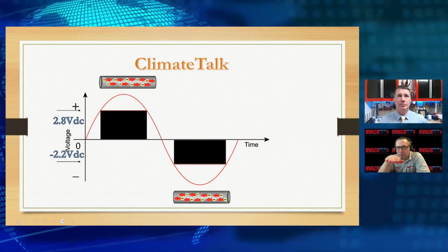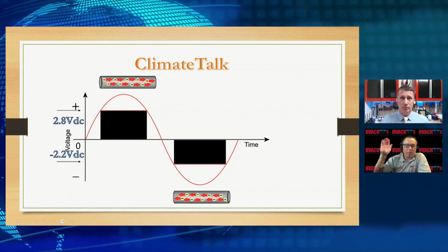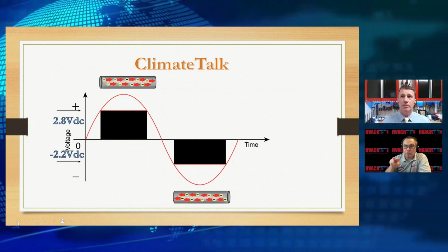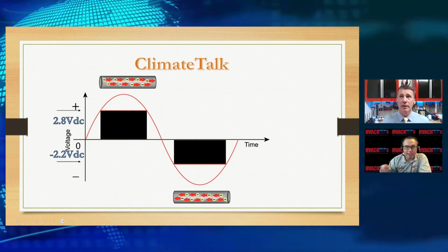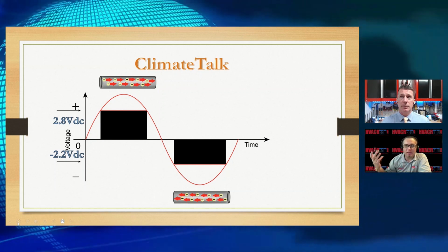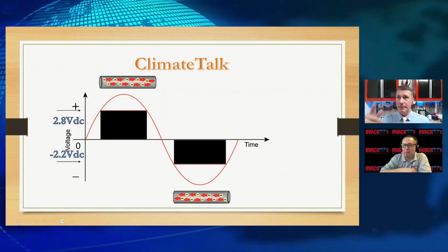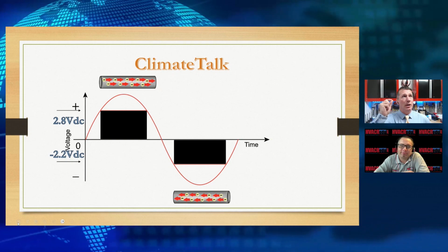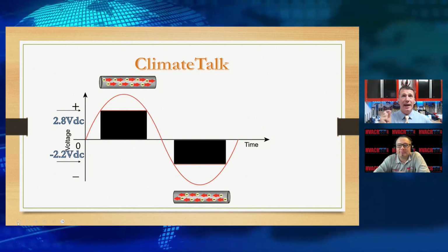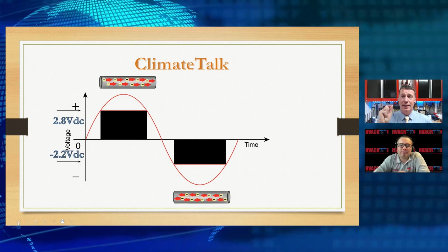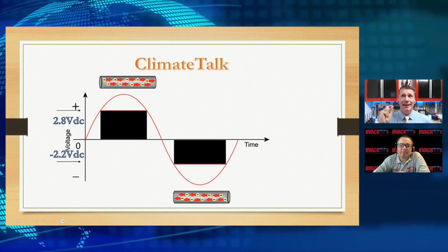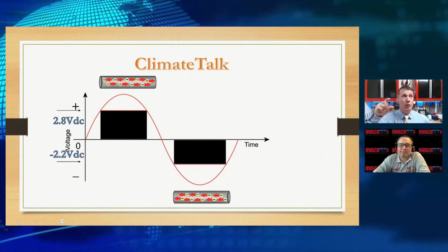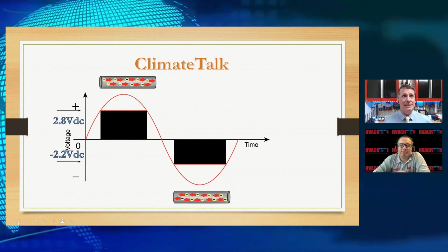All we're actually doing is setting that zero voltage baseline. I don't know if y'all remember, in some of the furnaces you plug in, if you have a 2-prong and you don't have that ground, all of a sudden your PC board doesn't like it. This is because we have no reference to ground, no reference point for our voltage. So those 2 wires, number 1 and number 2, have a reference to ground, and there's a difference between the 2 of them that we're going to call the bias.